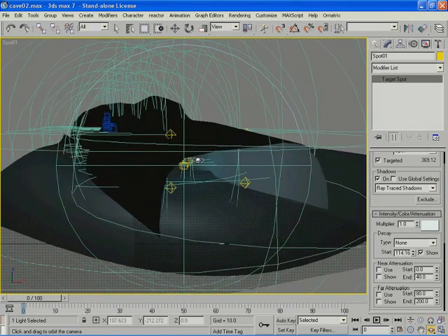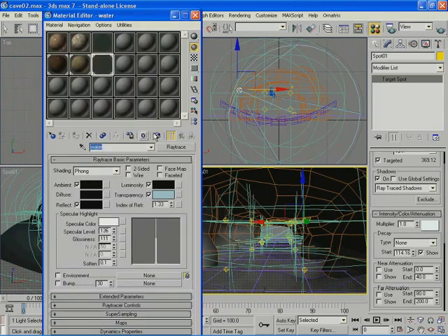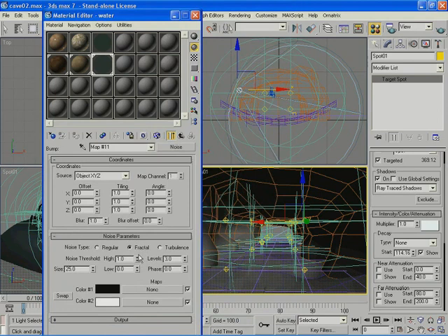Now, before I render, I also need to check Fresnel reflection for my water so that it reflects the environment properly, because water reflects the environment according to a formula which is built into the ray trace material using the Fresnel option. To get the Fresnel option, you have to check here once. When you check once, you can enter the value, but this will reflect planarly without taking into consideration the height of the geometry. So here I would check Fresnel, and I would add a bump map, which is a noise map in this case, and set it to fractal for now without increasing the levels. So just keep it low resolution here, or low detail. Save the file and give this a test render.